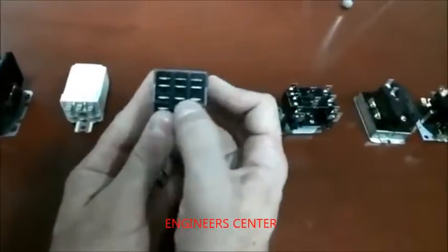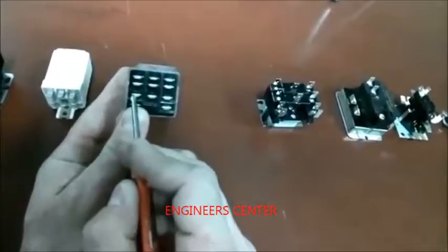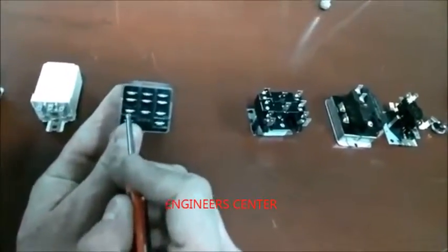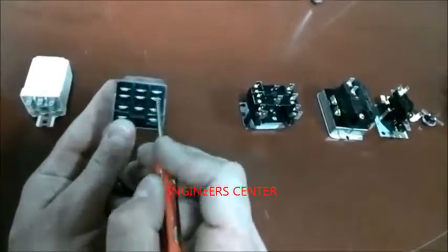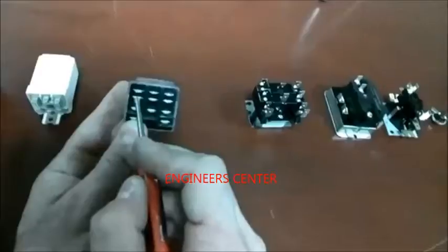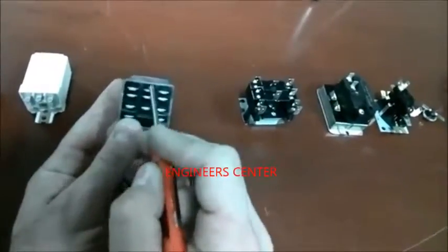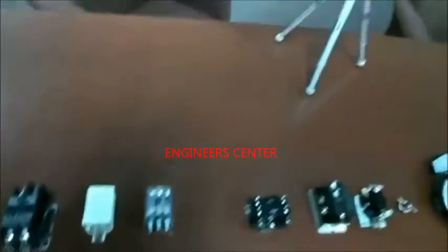You could put power here, here, here, or here, and this is normally closed to there, and to there. So these are closed, these are closed, these are closed. But if you give it power, this will now de-energize here and switch up to here. Same with all 3, so you have 3 different circuits. So you just have to understand what a part is and what it does in order to troubleshoot.